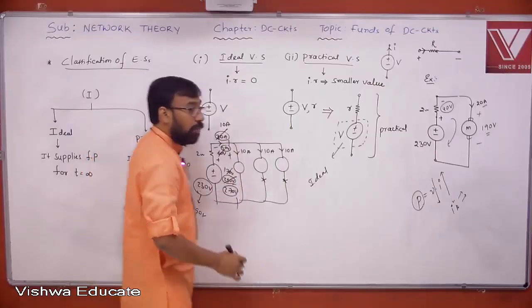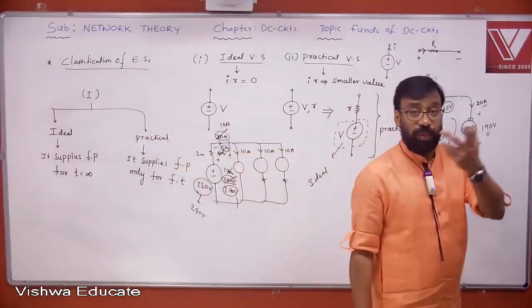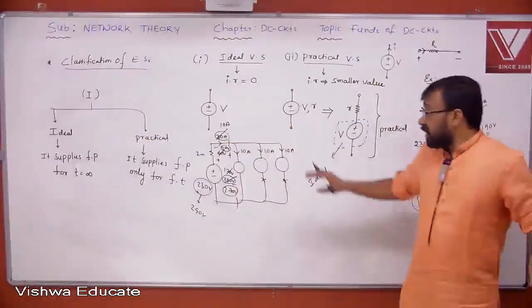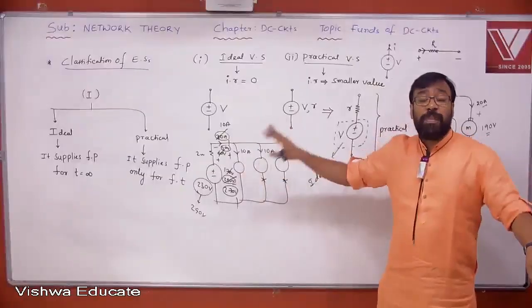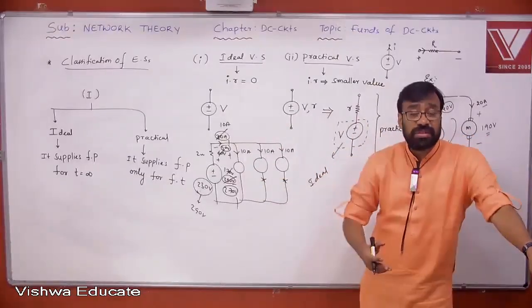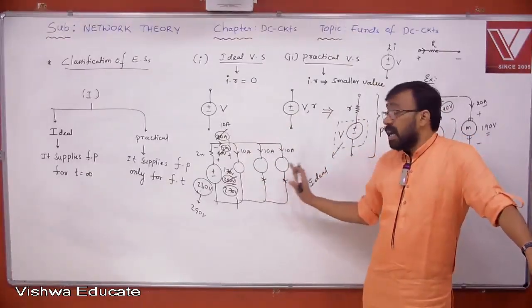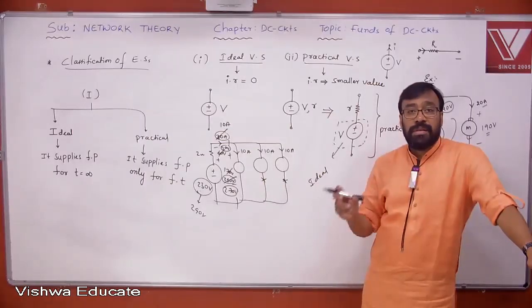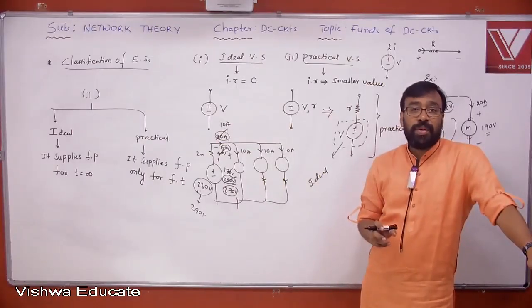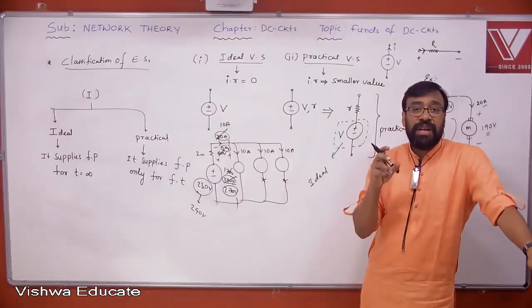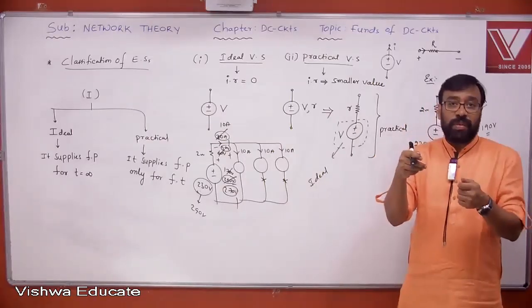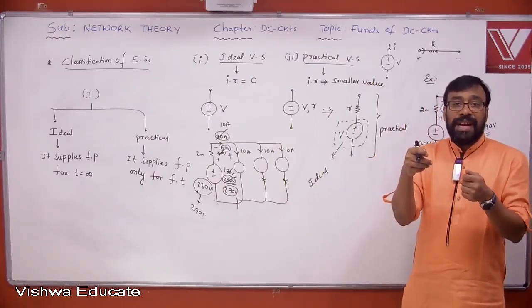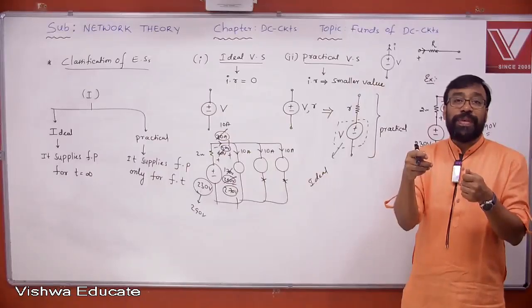Now this is becoming 270 volts. That means the motor is now operating at high voltage. The load which is in operation is experiencing high voltage when the other loads are turned off. What will happen when the load is operating at high voltage? Definitely every load has some insulation within, and that insulation has its own breakdown strength.